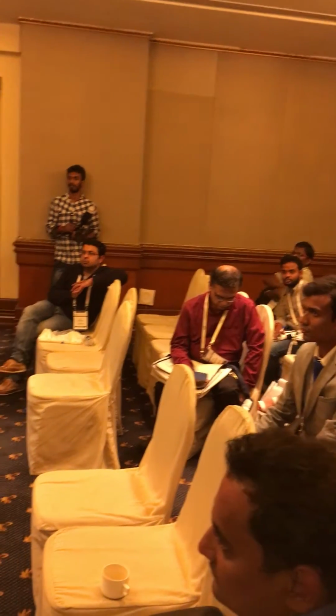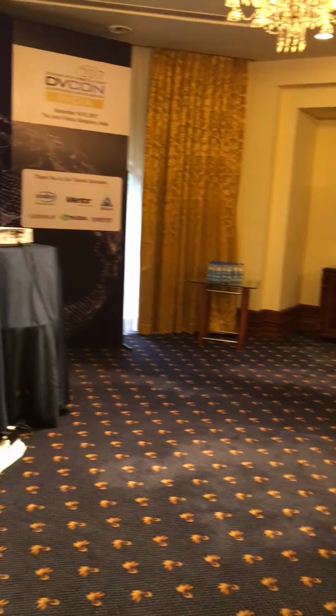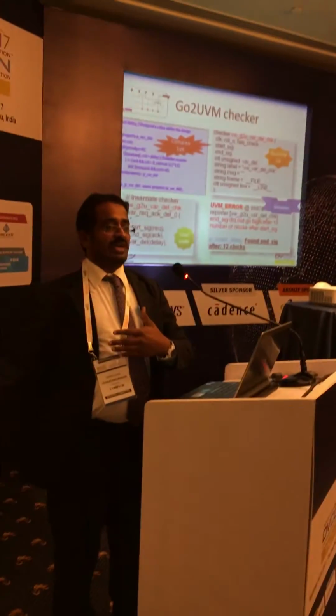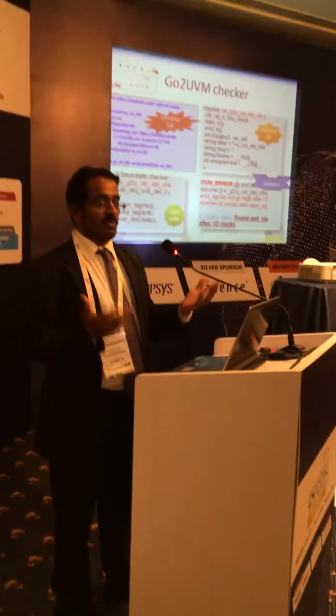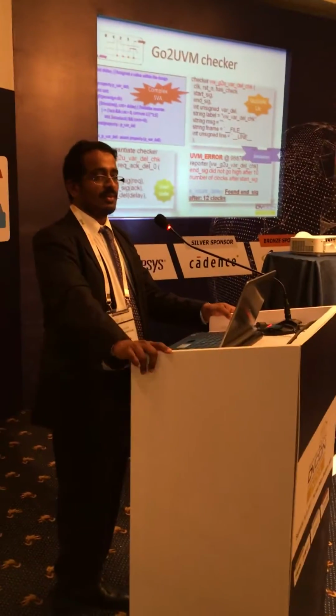The typical assertion would only fail. It wouldn't tell you when it found it. It was looking at 12. I was looking at 10, but the design gave it at 12. Your constant or the standard assertion wouldn't tell you. A checker would tell you, provided you code it. Of course, there's no magic in there. You'll have to code it.